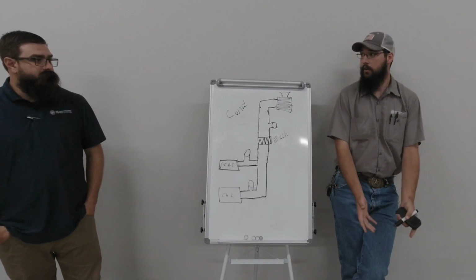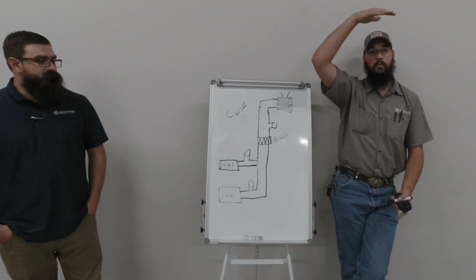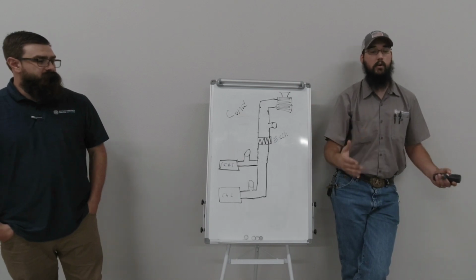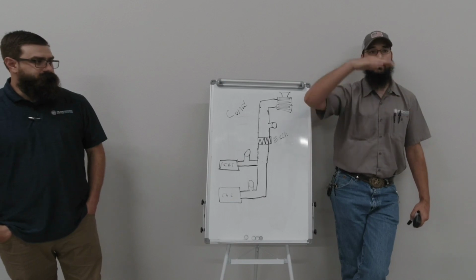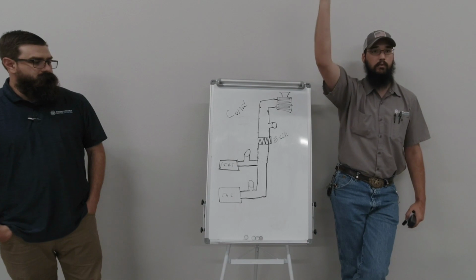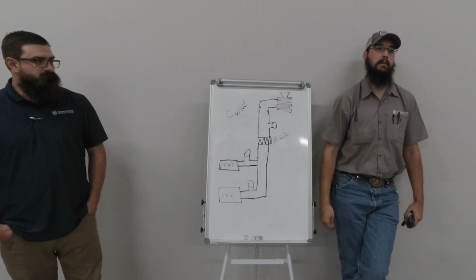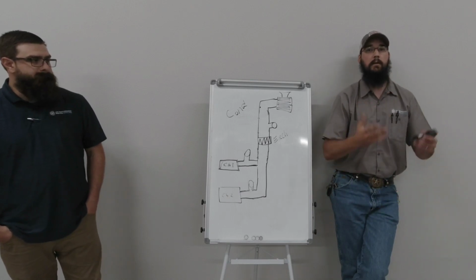And so say all the equipment's on the ground floor and you've got 20 stories, well, if everything's not balanced right and you have too much flow on all the equipment, those pumps may only be able to support flow up to 15 floors. Those top 5 floors may always have nuisance problems nonstop, strictly because they're not balanced well. And there's not enough pump there to overcome that imbalance.